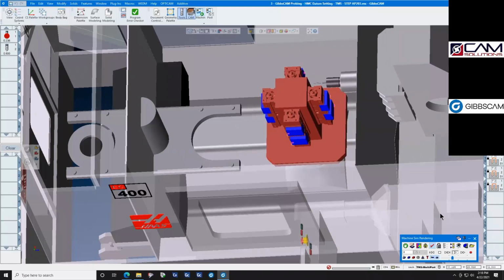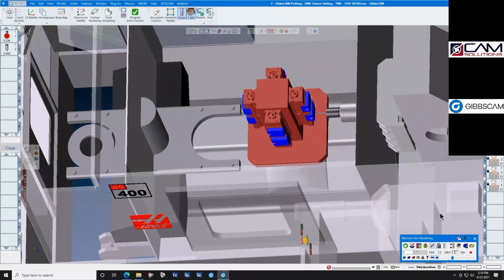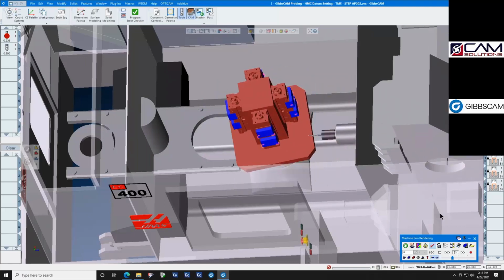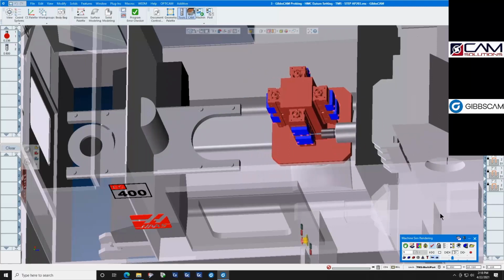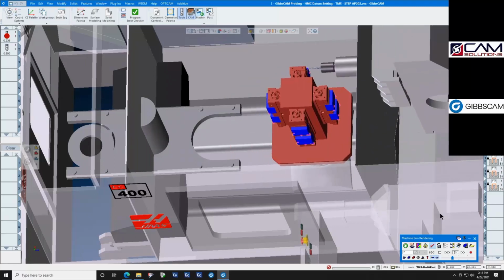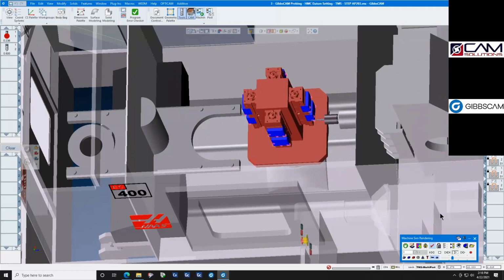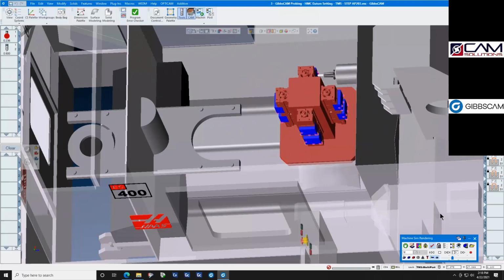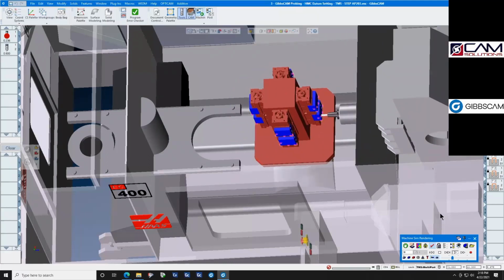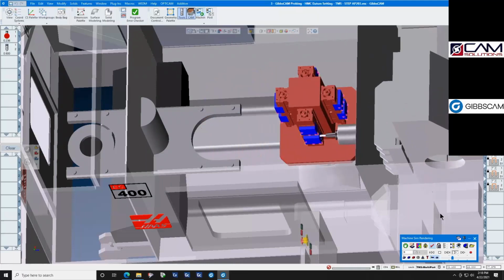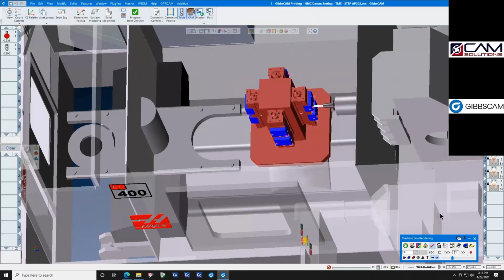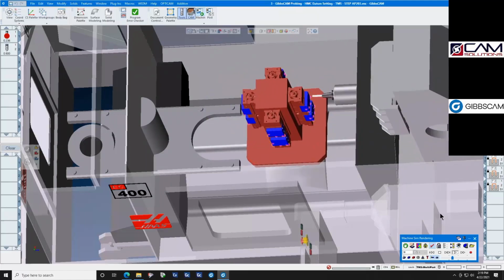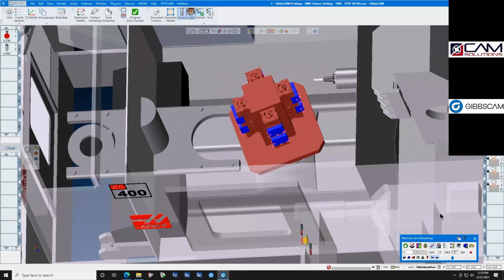Your decisions are carried out inside of the machine, even when you're home, asleep, and you have operators working in your plant at night. An unskilled operator can run this machine because the probe is now doing what you told it to do. The problems that you encounter without using the probe are inconsistency due to variations in your program cycle due to interruptions. Anytime that you stop that program to either measure the part or make an offset, you have created variations that can affect the quality of your part.